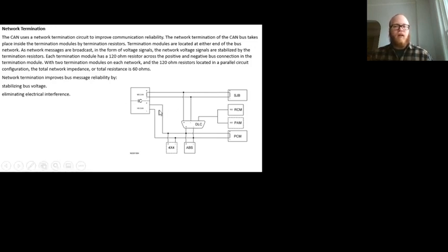The use of doing this ohms test is, if I had an open in one of my wires or one of my resistors is burned up, I'm going to see that 120 ohms. So I'm going to know, oh, I've got an open somewhere that I need to diagnose.